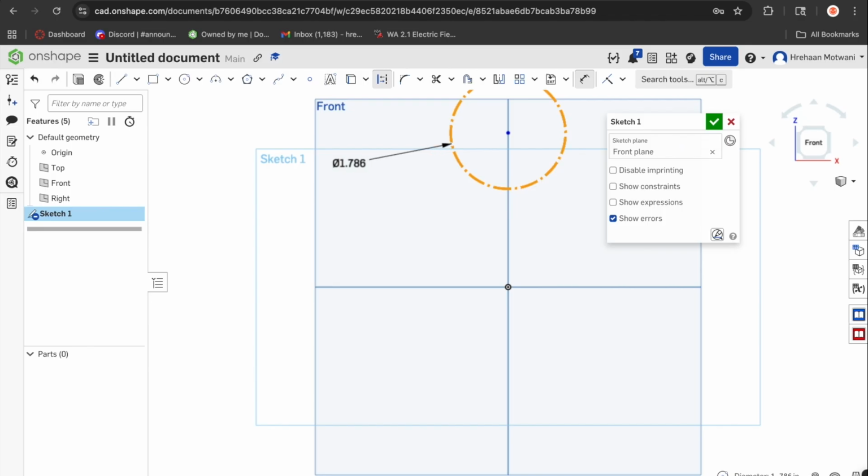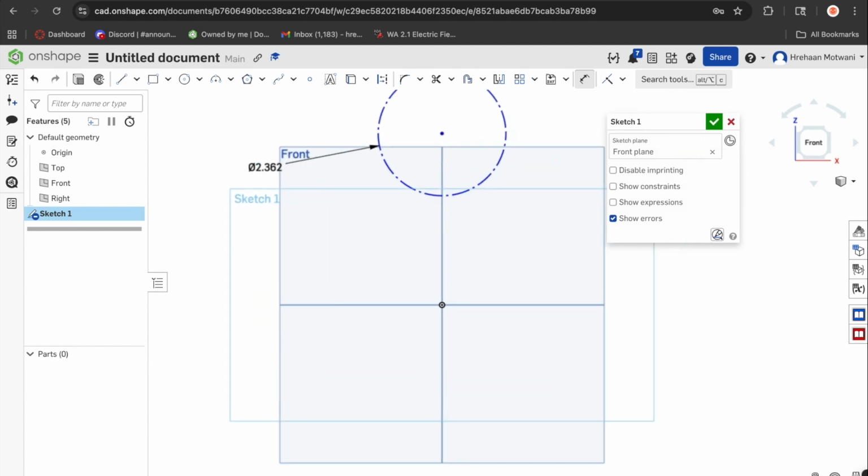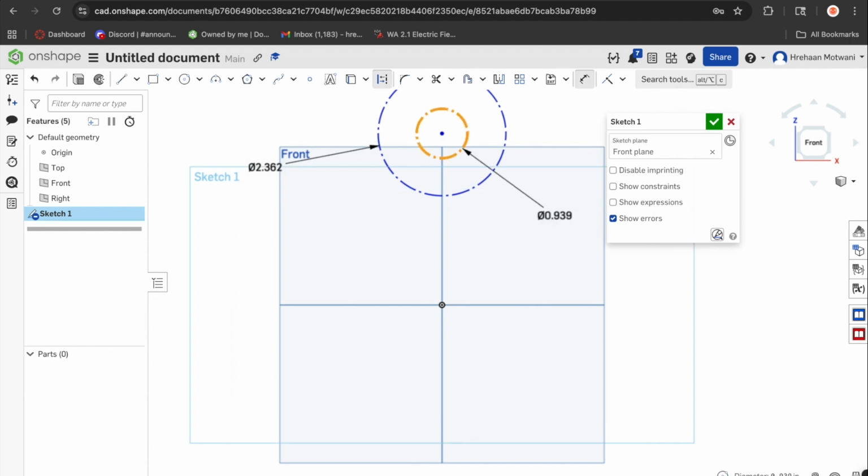Okay. And we're going to use a Kraken X60, so the diameter is 60 millimeters. And then we're going to create our two gears. The way you CAD a gear is basically the size is the number of teeth divided by the DP. Since we're doing a 12 tooth gear, it's going to be 12 divided by 20 DP. DP is the diametrical pitch of the gear.